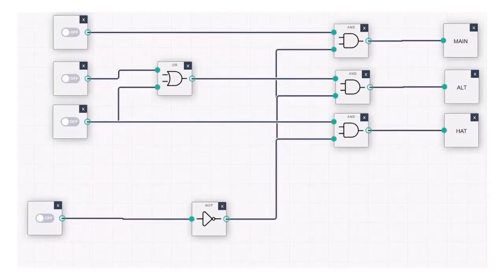We'll take another look at our elevator. What we've done is we've added a bypass switch here in the fire panel to prevent elevator recall from happening when you press the switch. So if a recall event occurs, if you hit your bypass switch, it turns it off. See how that works?